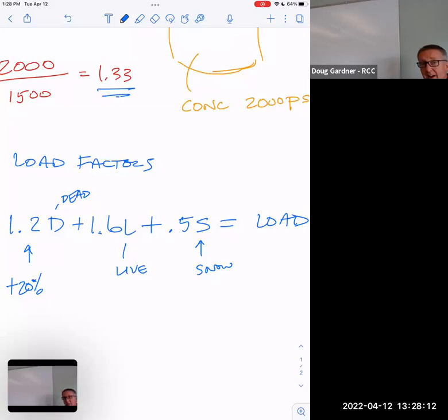It's like, was this likely to happen? So this little formula that they put up there, they pointed out in the book, it's not likely that the maximum live load that's weird, not just 100%, but 160%, because something weird happened, is going to coincide with a huge snowstorm. So we don't need to add a 1.6 snowstorm on top of a 1.6 live load, because it's unlikely that those two things will happen.